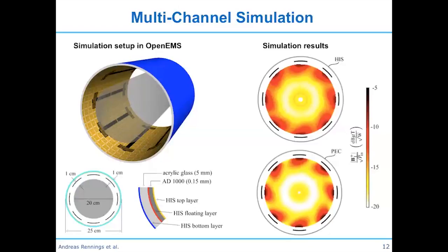So it's kind of a field singularity thing. That's why it's not plotted. But Maxwell's equations are evaluated in a proper manner. The Ez component would be at the center, and then the circulation of the magnetic field around is considered. So Maxwell is solved there, but it's just not plotted. So it's not a big deal.